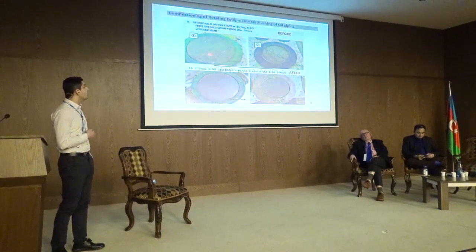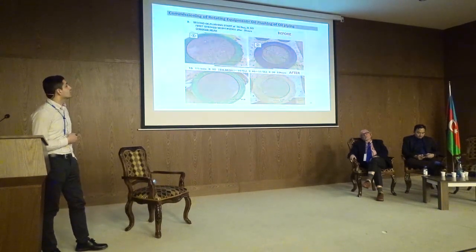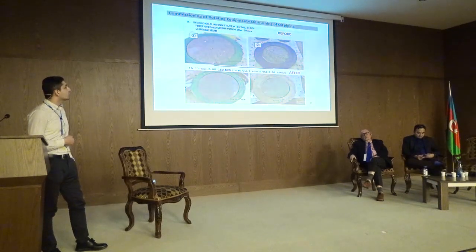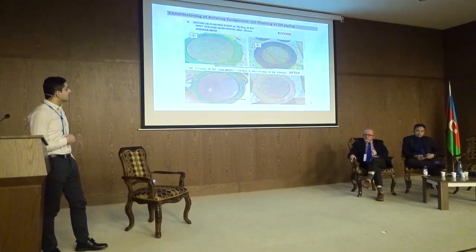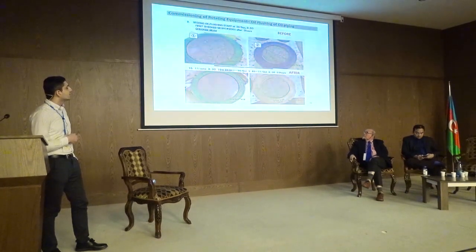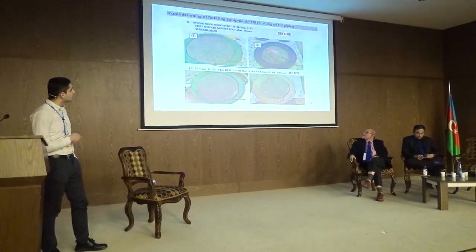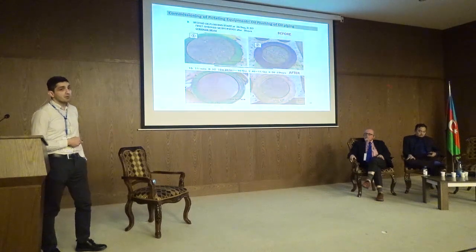And the top meshes were removed after the second flushing, whereas the bottom meshes were removed after the 15th flushing. We did 15 flushing recirculations, and it took about 2 weeks. As you can see, the top meshes are quite dirty, but the bottom ones are very clean.